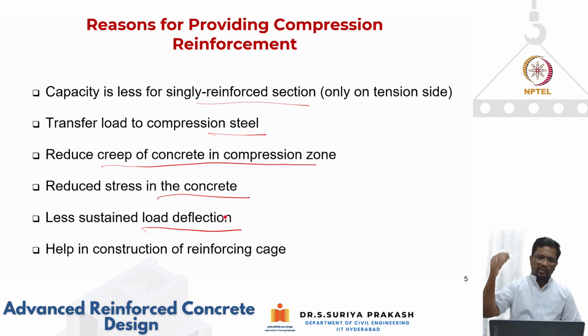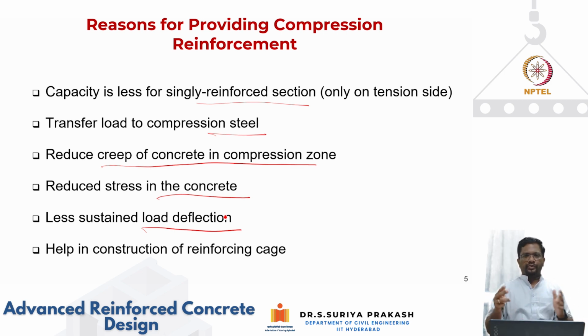Also, some level of compression steel is required to hold your stirrups while you make the reinforcing cage for a beam. So for that purpose also, and from a ductility point of view also, we add compression steel.